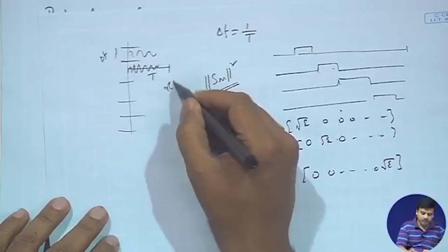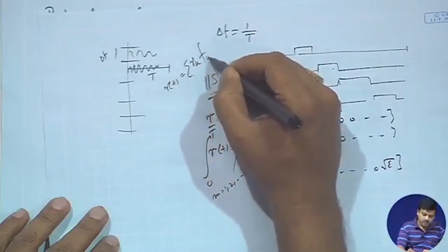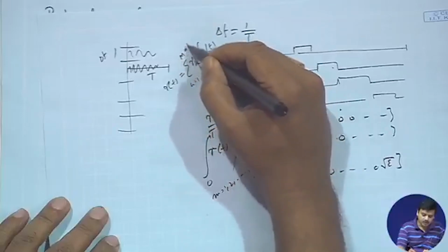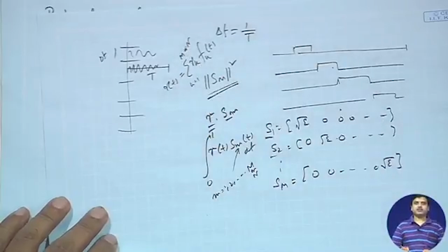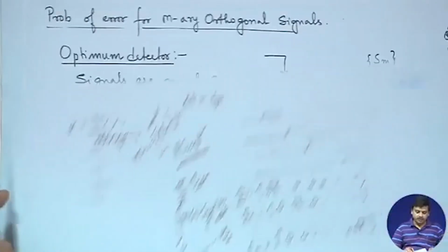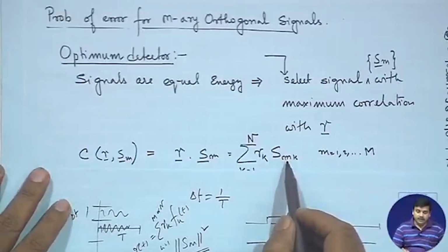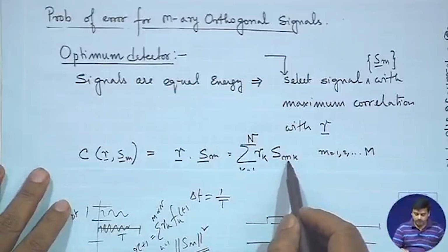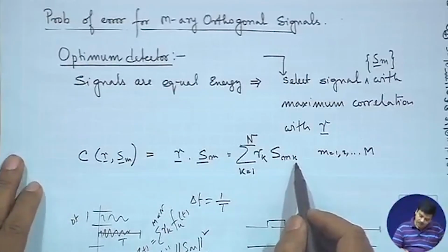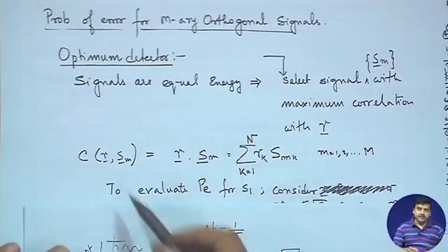The received r(t) would be broken into the sum of r_k times f_k(t), k equals 1 to M or N, either in this case, it is the same in this particular situation. The same applies to this or any other constellation which may make sense. So, m is the index for the signal waveforms and k is the index of the basis function. So, this is a generic expression.